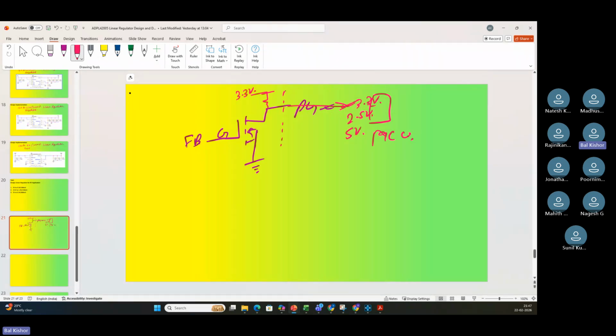So the logic level always changes. It is not possible for the manufacturer to give an internal power supply for this drain, the drain of the MOSFET. That is the reason they have told you: I don't want to give you any voltage level here. It is your duty to pull this up, so whatever way you want, you pull this up.